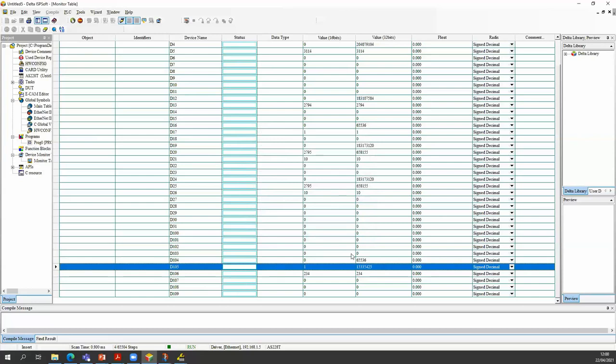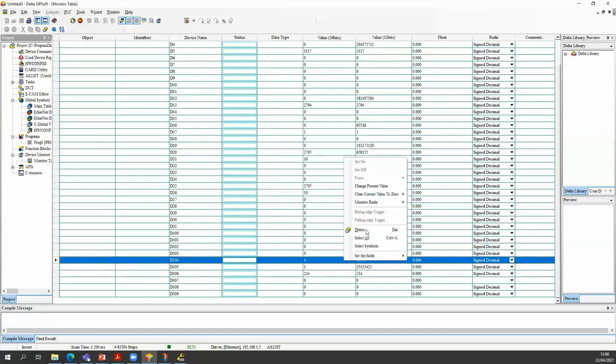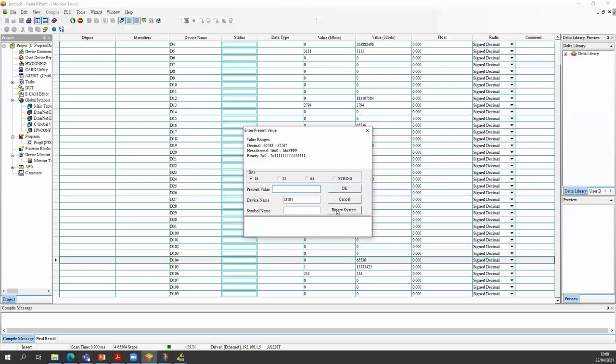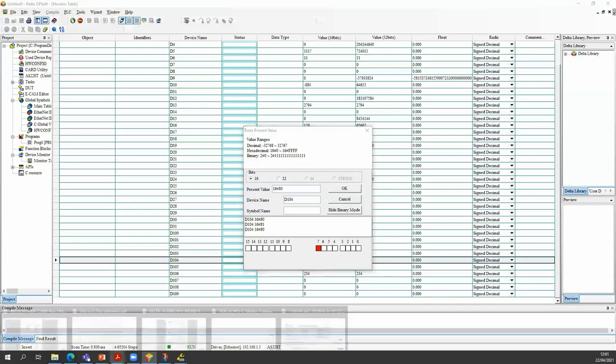Okay. I'll give a run command firstly. So servo on, and I can see the frequency is set to 0. For positioning mode, if I enable this, this will be the command to move to a new position. But if I enable this, then nothing happens because I've not given it any position command.